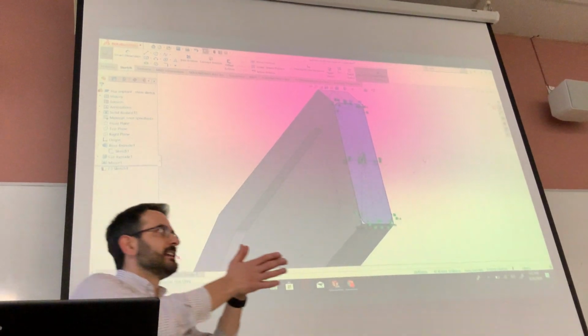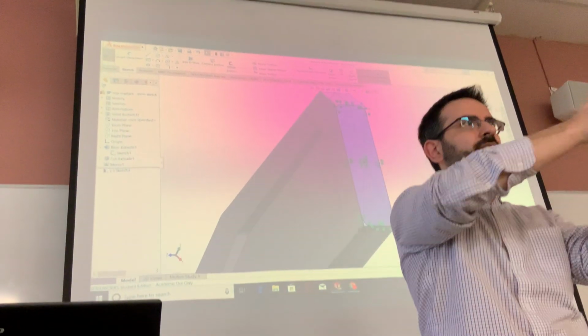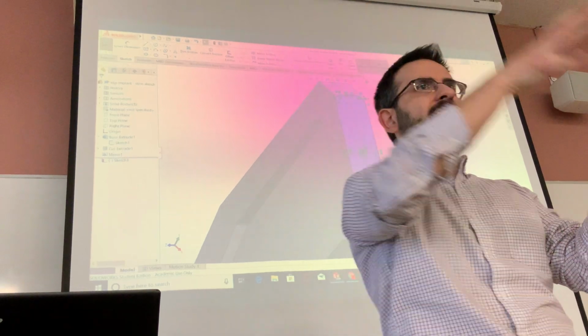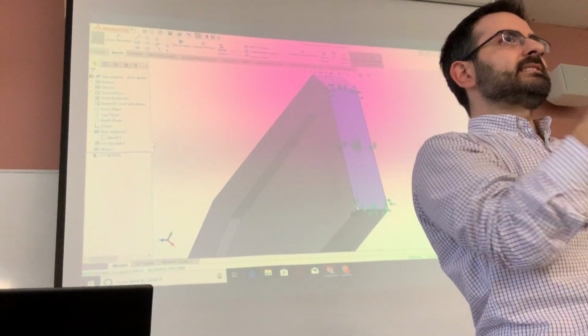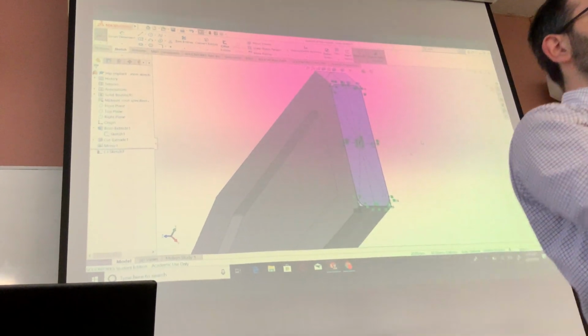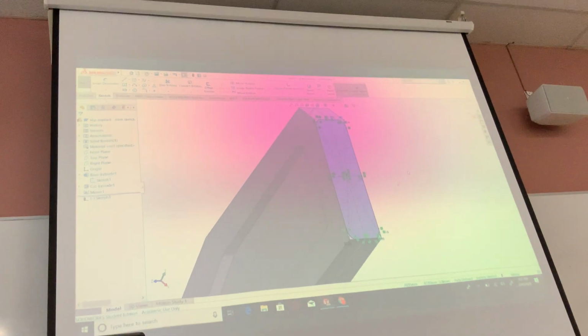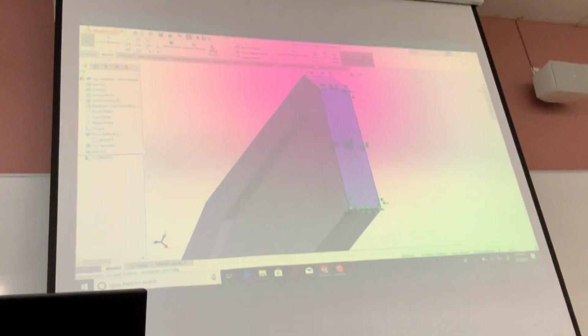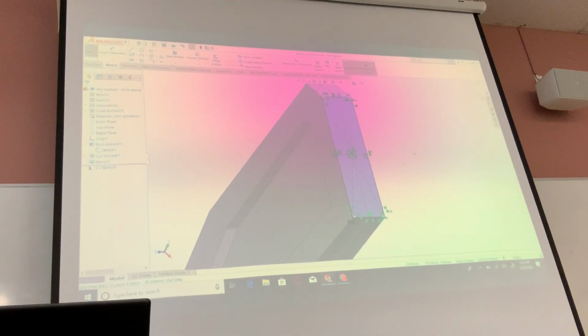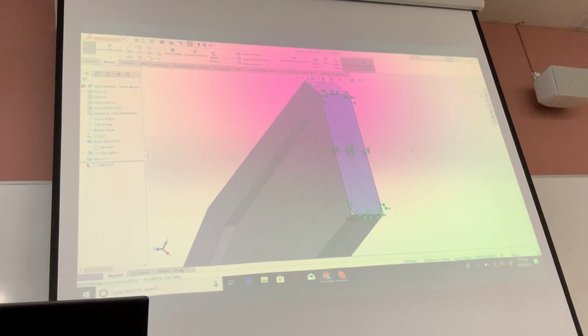Now, again, I need to create another plane where I can put the end of that neck, because this neck is a more complex geometry that goes from having a base that's a rectangle with rounded corners to a circle. That kind of operation in Solidworks is a loft.